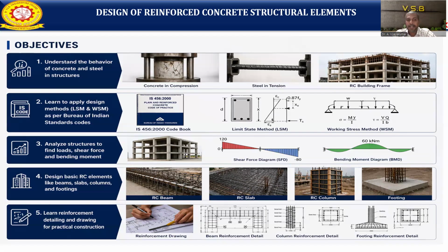Then learners should analyze the structure to find the loads, shear forces, and bending moments for the various types of load. Because once we know the bending moment as well as shear force only, we can give the reinforcement details also. That's why we should know, based on the cantilever beam or a simply supported beam or a continuous beam, what else the beams will be there.